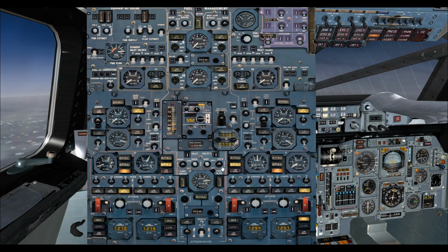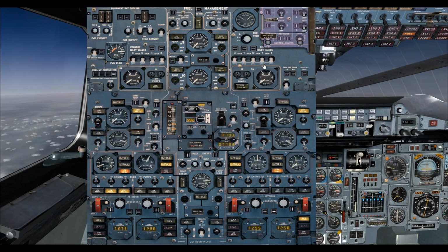which means the engines are running off whatever fuel's in the collector tanks, and engine 1 is almost out, and engine 4 has actually gone out. Now it hasn't in this case, but we're going to wait for it to starve out, which will happen any second, and then I'll show you how to do the relight on the engine.